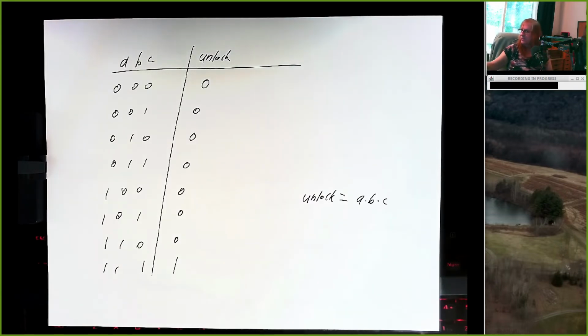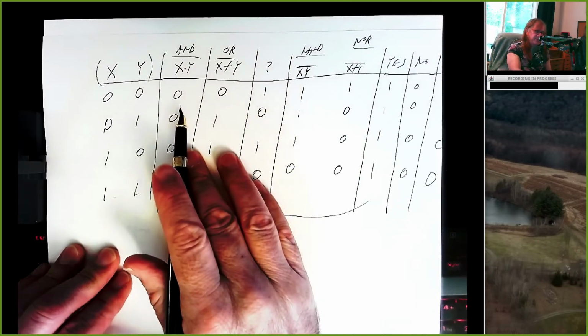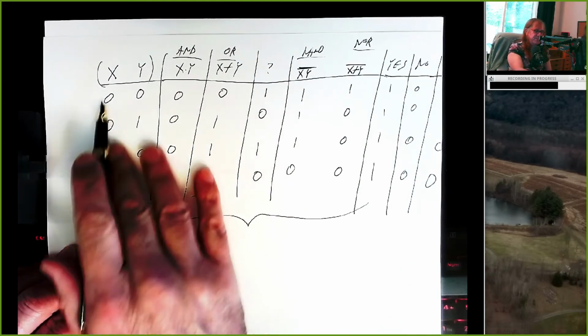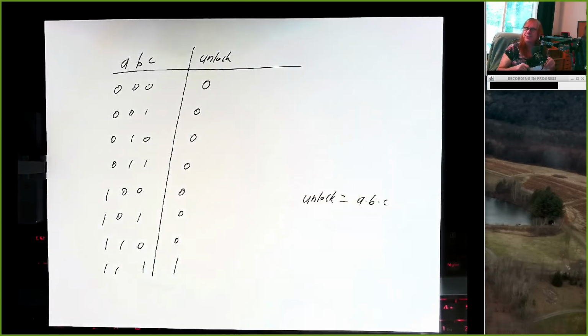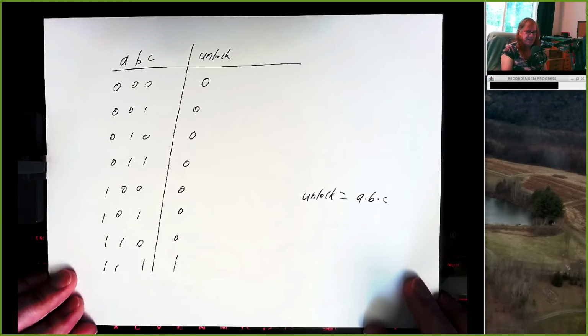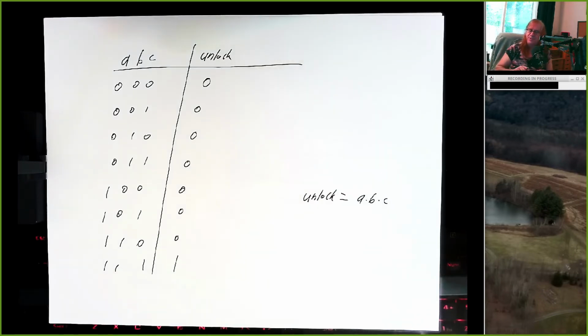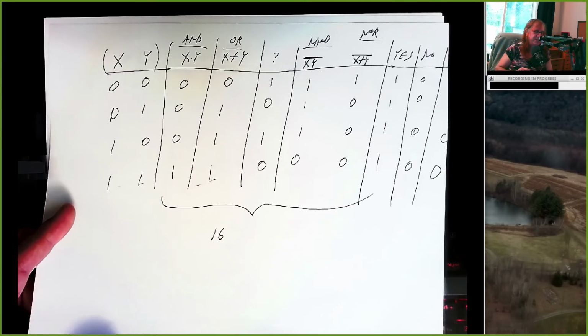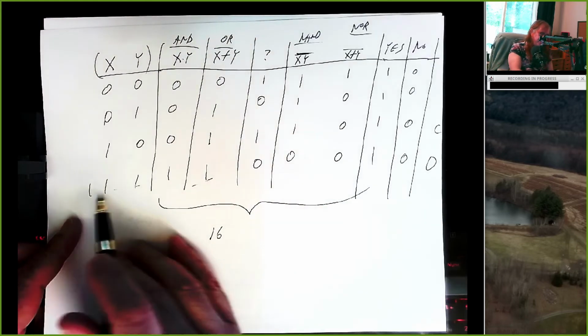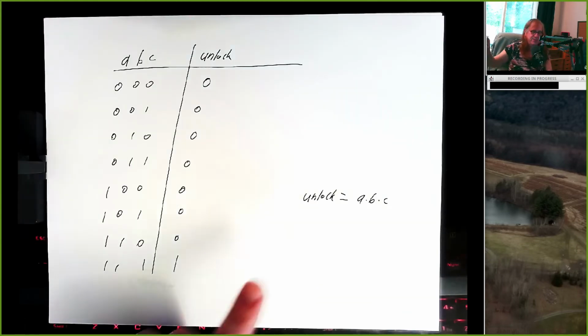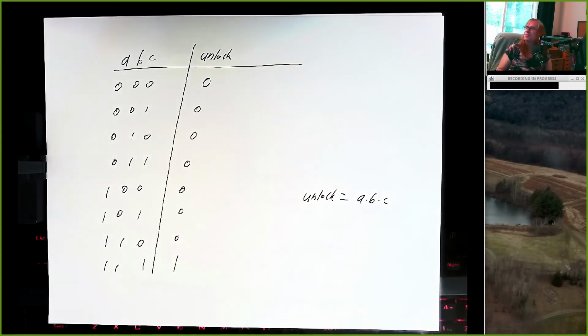Well, it turns out that, just like there's an AND operation for 2 inputs, we can make a truth table for an AND operation of 3 inputs, and it looks exactly like this. So in addition to having picked a password that nobody would ever think of, I also picked a password which makes my circuit really super easy to design. Because I can find a physical piece of hardware called a 3-input AND gate, and if I put 3 1s into that gate, I'll get a 1 out, and every other time I'll get a 0 out.